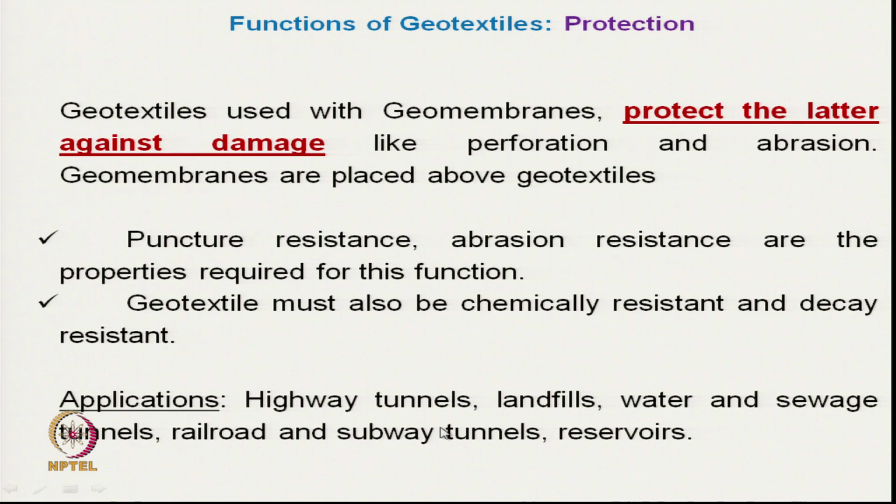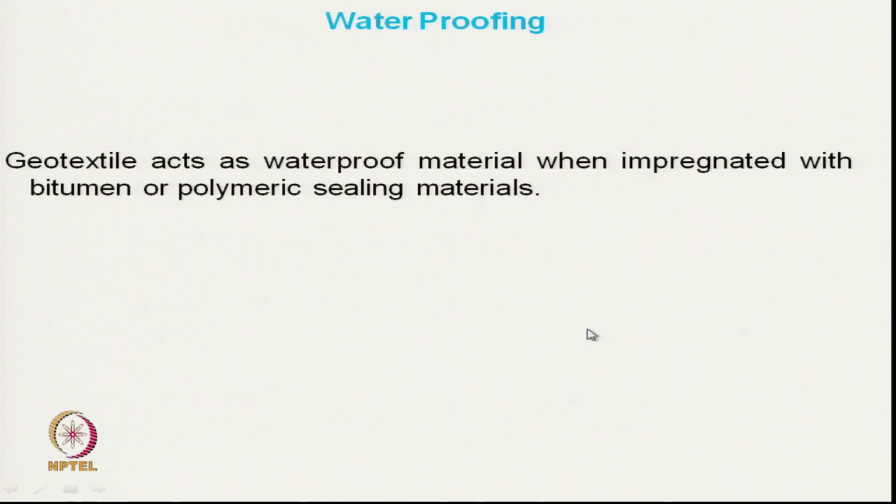So, in landfill, water and sewage tunnel, railroad, there we can use geotextile for their protection purpose. Waterproofing is also used when geotextile acts as waterproof material when impregnated with bitumen or polymeric sealing materials.